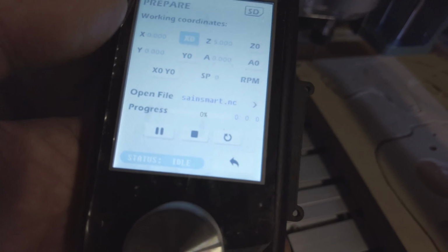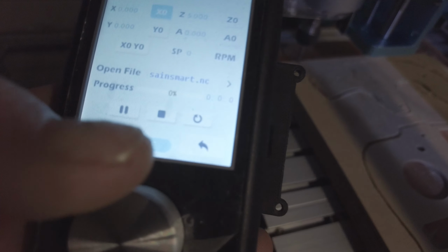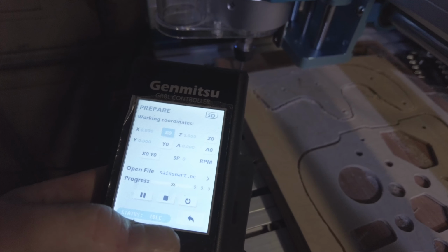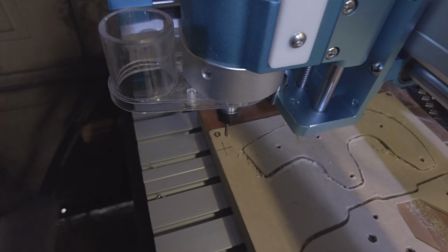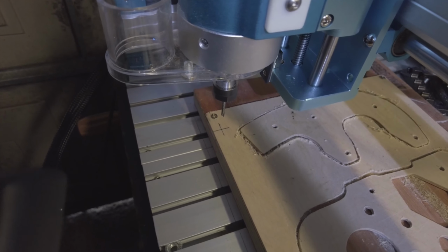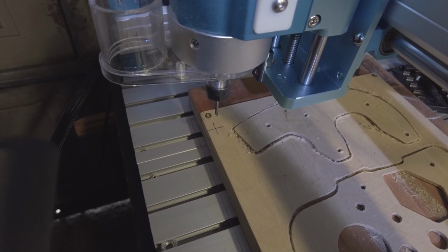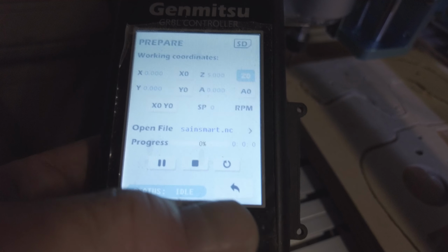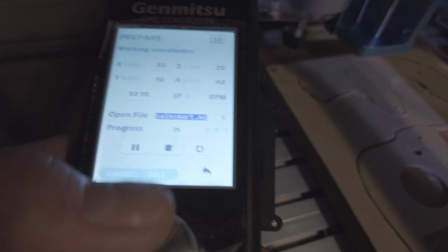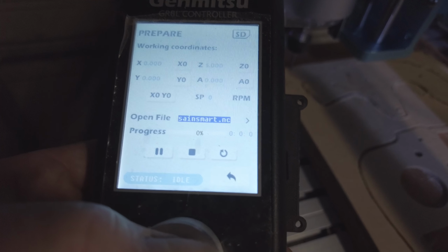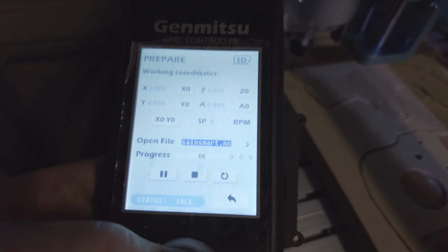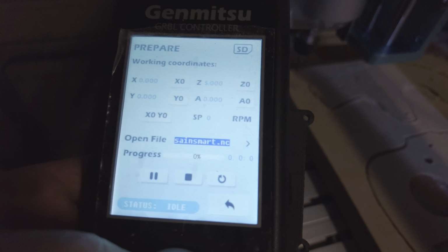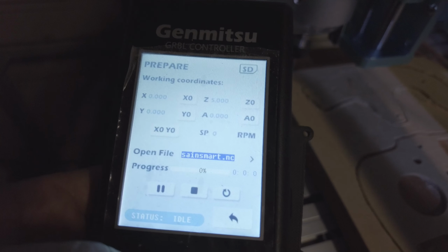So right, now what we do is, if you wanted to just change the cutter while it's there at that particular point, you could do. You could just touch off and then you go back down to your open file there and you would just install the next toolpath, okay, and that toolpath would carry on exactly from those work coordinates.